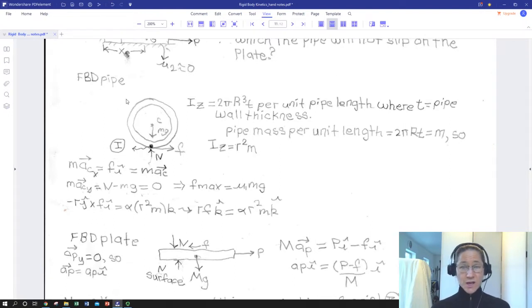Because we're talking about forces, as well as motion, we're going to start with FBDs. And as an aside, since we're pretty darn sure we're going to want to relate something about the moment applied to that pipe, we're going to quick draw our polar moment of inertia of the pipe cross section right here while we're drawing the FBD. We look this up for a thin-walled pipe.